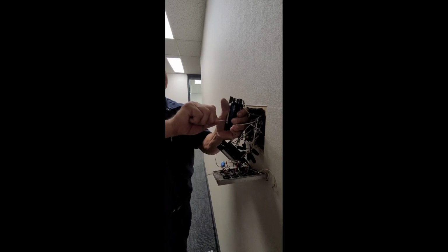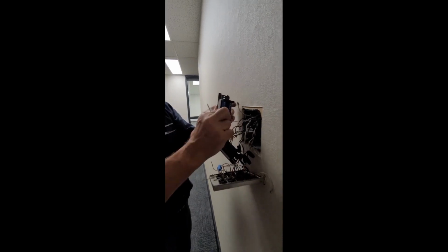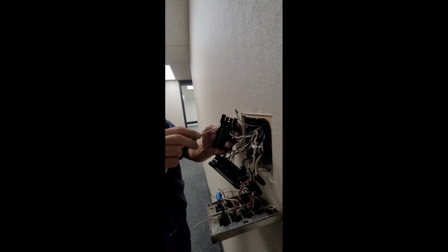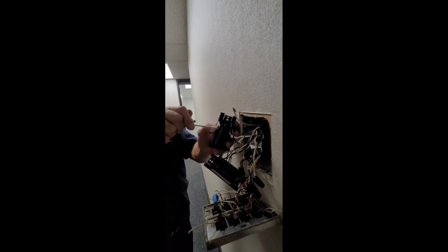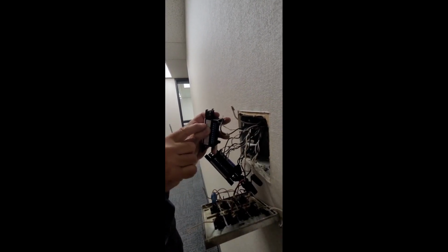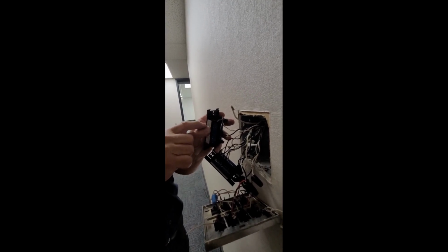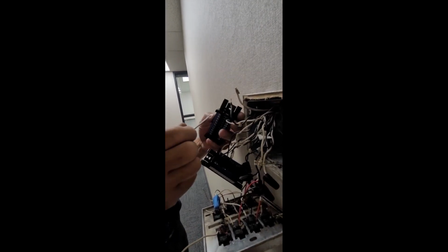It's tight. Make sure it's tight. Always do a wire pull. And then we said that the off wire, which in this case is black, is going to go to switch 5. And we do not connect anything to L terminals, which is the light terminal. So we make sure we only connect on S terminals.